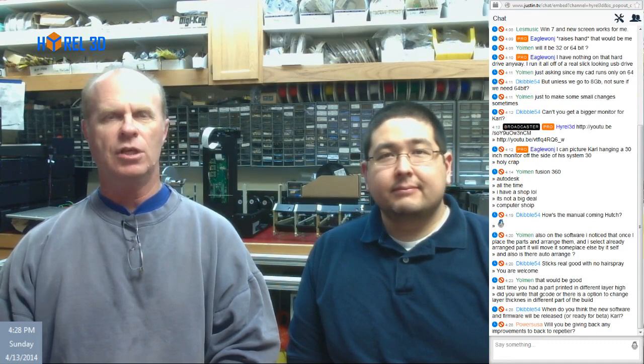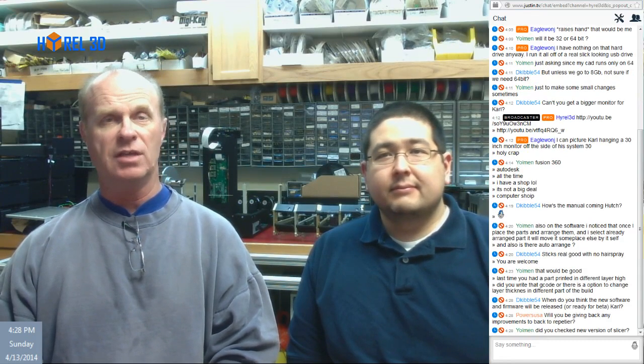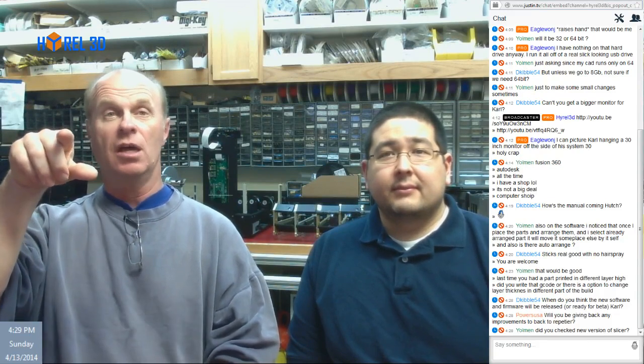I think what's going to happen also is no one's doing a G2 or a G3. I think we're going to be the first ones to support it that I know of. And so the G2, G3 changes any round object, because now you can literally in one instruction do an entire circle. That makes building the columns of desire really simple. A cylinder is, you're done. It's one line instruction instead of what could be hundreds of lines of code. That cleans it up, and it's easy to auto-generate it that way. And because it's a pure arc command, there are no funny patterns that go around it.